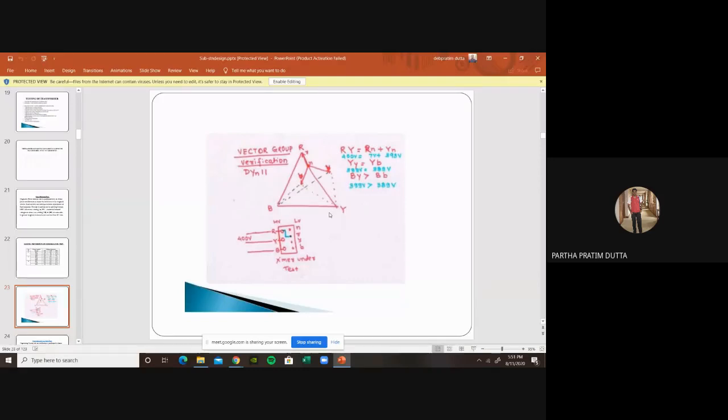In our 33 kV and 11 kV substations, the power transformer usually has the vector group DYN11. Now you can ask me why it is DYN11, why it is star on the LV side. As I have shown you in transmission, we usually use delta, because with delta we can use 3 wires. But when you use star, you have to utilize a 4th wire as a neutral.